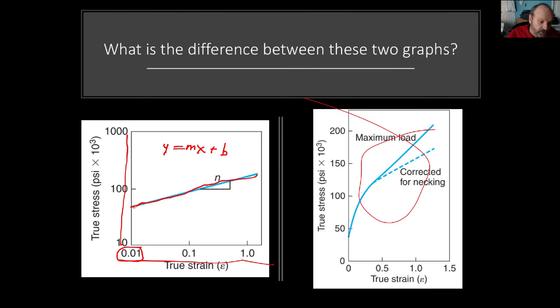If we were to go to 0, you'd probably see something that comes almost straight up, a very high slope, and then it bends over when it gets into the plastic region. And then it finally breaks. This is where it breaks. So you can look at this and say, oh, when it gets twice the length, it breaks. That's another thing you can see from this graphic.